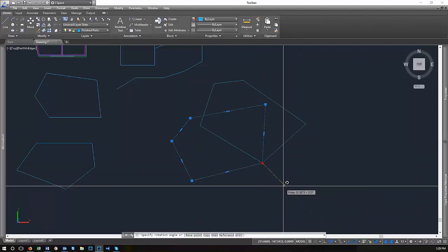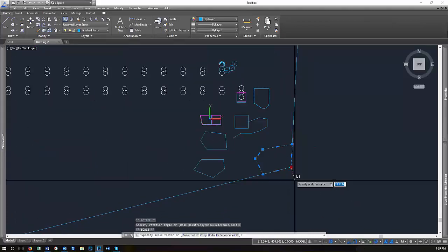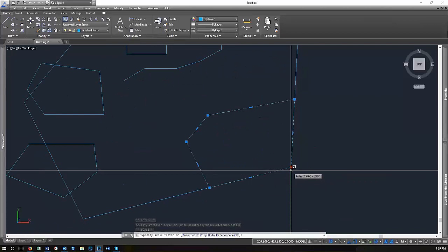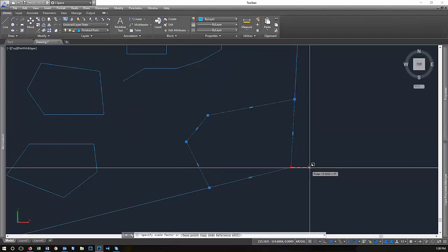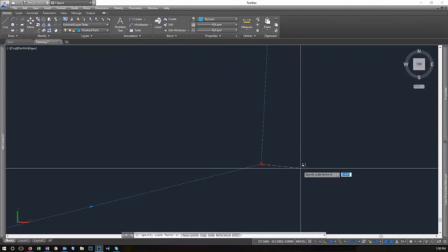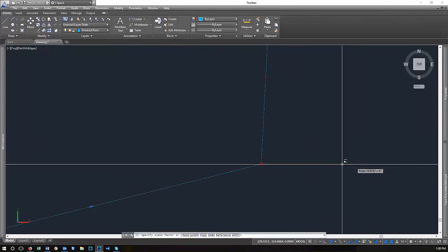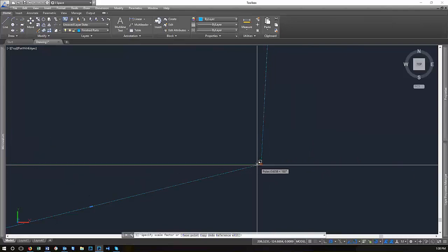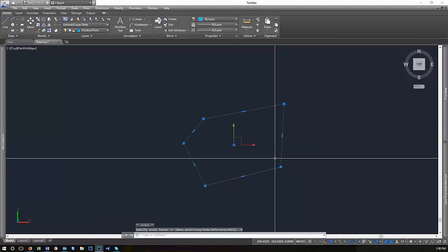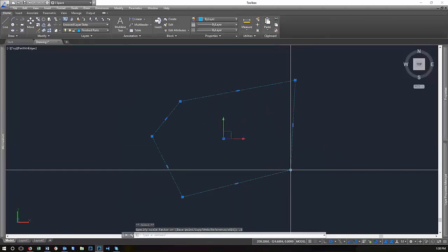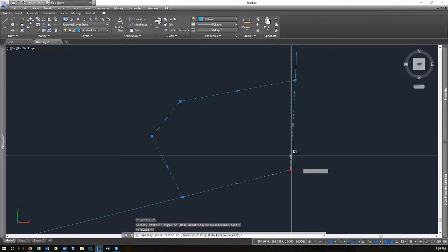So you can hit rotate, or you can hit spacebar again, and it's now a scale command. Scale is a little harder to use for this one because typically you don't want to go more than double, but it bases this command off of your units. So right now I'm at a scale factor of, and then I drag it out, it's at 14, 19, so it's becoming 19 times the size. So if I wanted to make this half the size, I type in 0.5, and now it shrunk half size. So that's the third command on the list, scale. So stretch, move, rotate, and then scale.